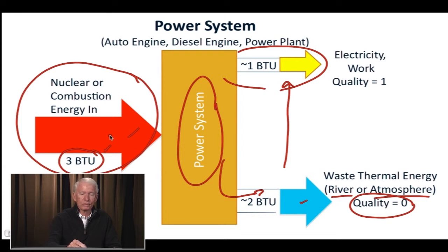Before, if this was 240 degrees Fahrenheit, we could upgrade theoretically as much as 29% of that and throw away the other 71%. But that's the limit that the second law places on us, and in real world processes, we can't do that well. We try to approach it, and if we spend more money on the power plants, we can get a little closer to it, but that's what the second law of thermodynamics does.